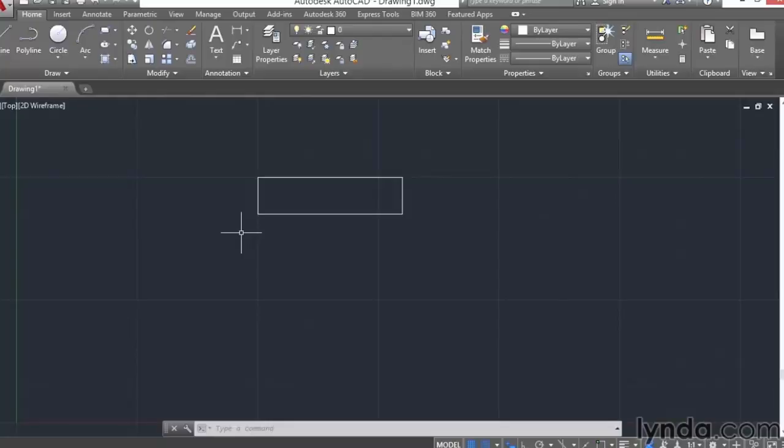A more flexible approach that we'll cover in a future video is Object Snap, and that allows you to snap directly to geometry that you draw in space. But this more primitive or more fundamental system of Grid and Snap allows you to draw objects that happen to conform to a regular grid. So let's go ahead and draw another line here. And you see that I can't draw it to any place other than this spatial grid.